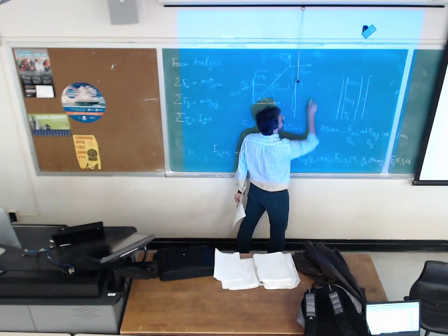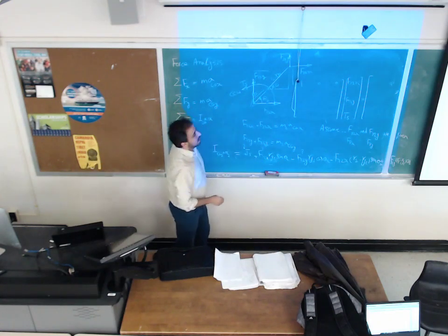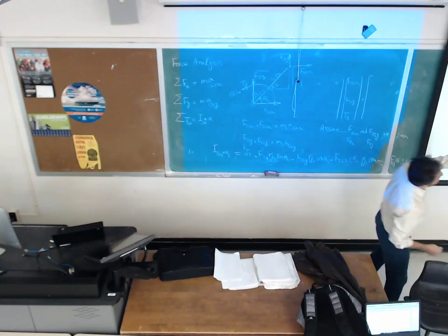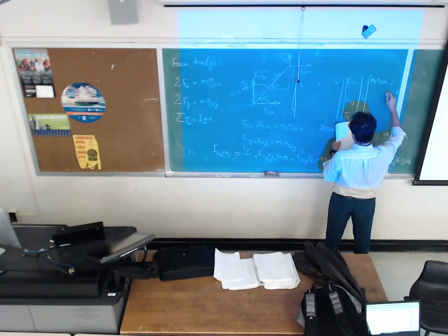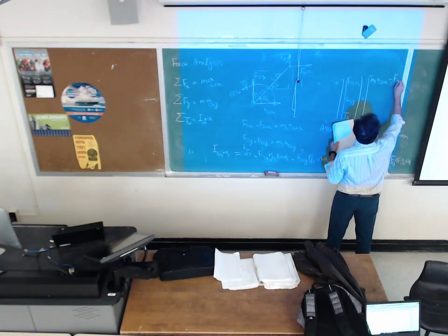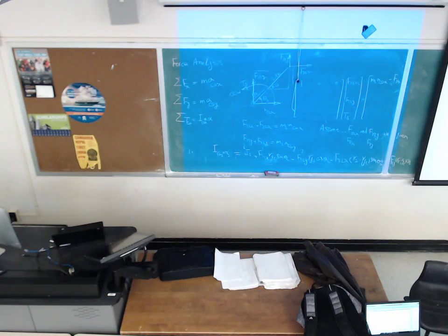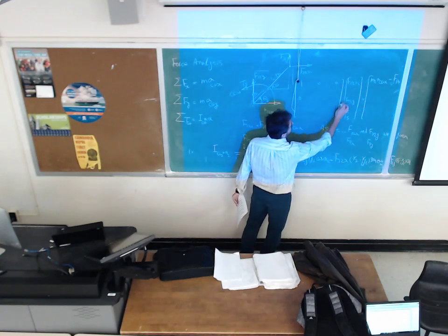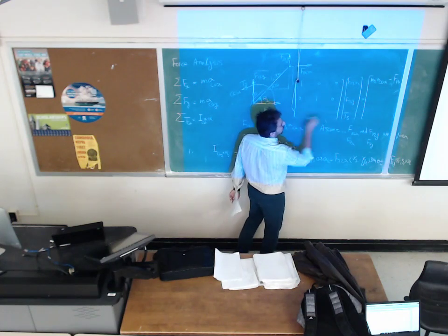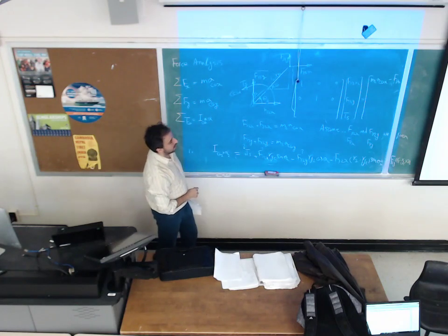Right-hand side, we have m2 times acceleration of center of gravity in x, minus FPX. Second equation: the coefficient of F12x is 0, the coefficient of F12y is 1, and there is no TS. There is no torque showing up in that equation. And this is going to be m2 times acceleration of center of gravity in y, minus FPY.